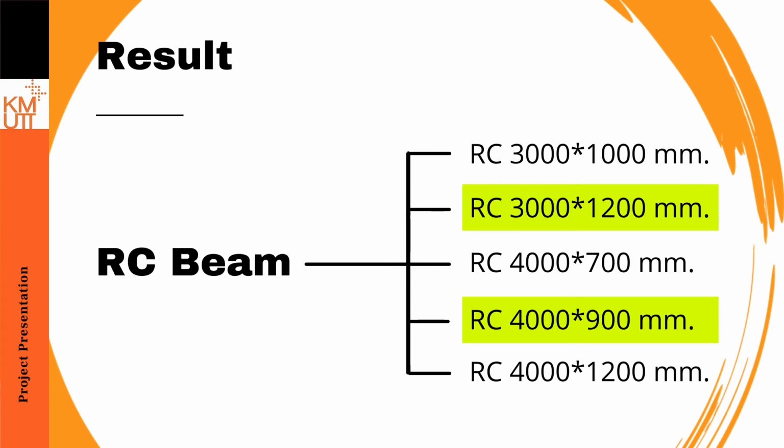For the reinforced concrete beam, there are 5 module sections designed, different in size and reinforcement detail. For all sections, the spacing of stirrup bar is 15 cm, and we use this spacing along the beam, since the slight decrease of shear force means that shear at the midzone and the end zone are almost the same. And the longitudinal bars are designed as skin rebar for preventing surface cracks.